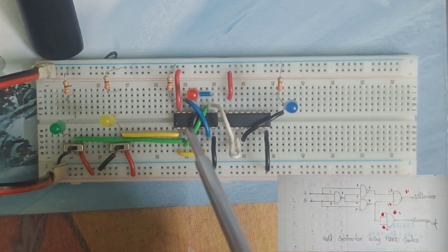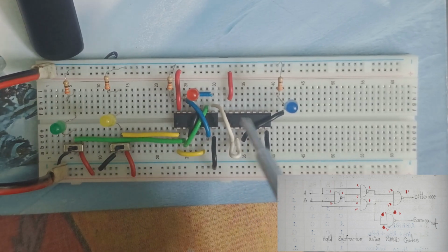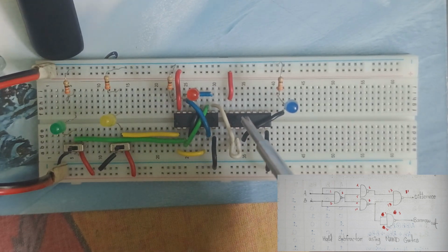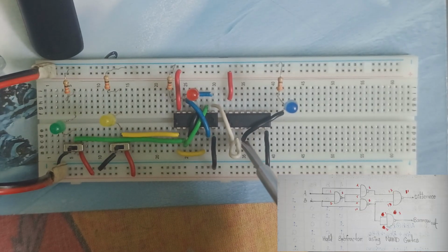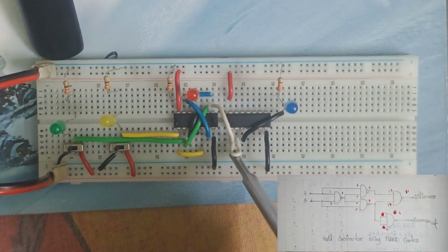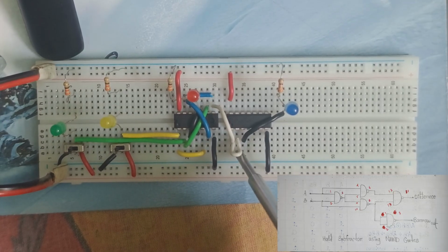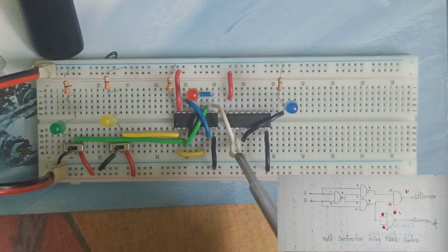This circuit is very common in most of the circuits, and this particular IC I am using just for a simple one NAND gate, and that NAND gate is acting as a NOT gate because I have shorted pin number 1 and pin number 2, both input terminals, with this white wire, because I need a NOT gate here. How to get a NOT gate from a NAND gate? The answer is simple. We just need to short both input terminals.